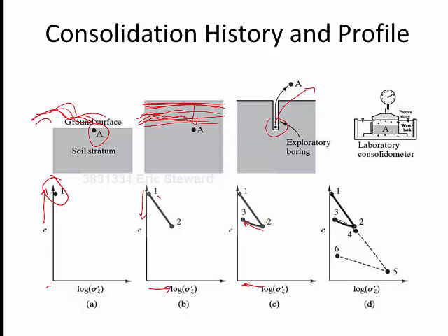And that new behavior is what I like to describe by saying soil has a memory. It knows the largest amount of stress that has ever been felt in its history. Because the soil particles have been rearranged and moved, the void ratio does not rebound the same as it did in its original structure when it was first formed. So when it's retrieved from the ground, the stress is reduced, but the void ratio is also reduced, and not back to its original state.